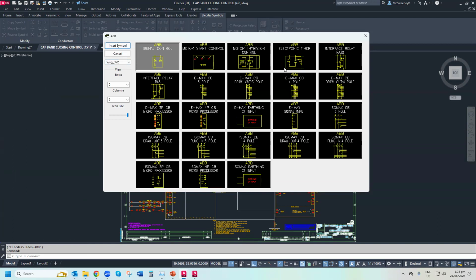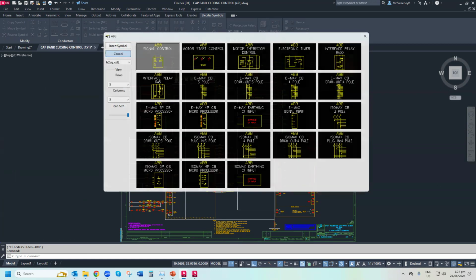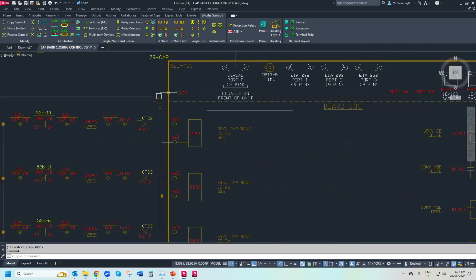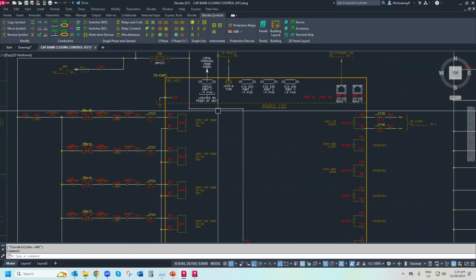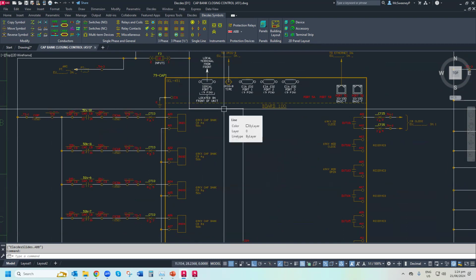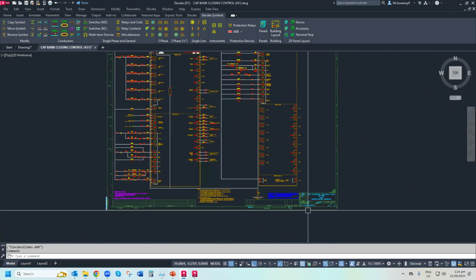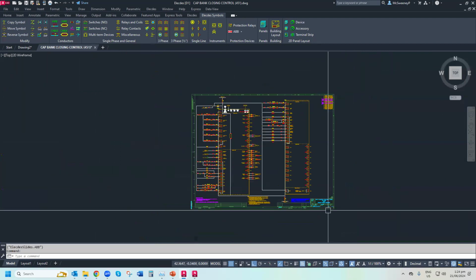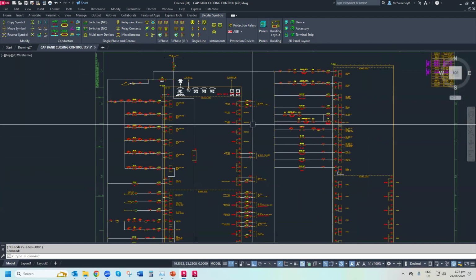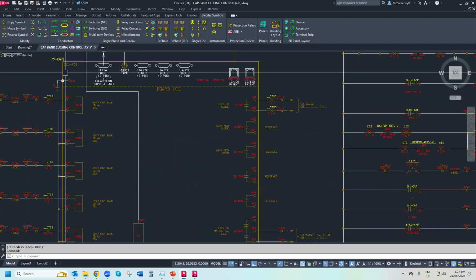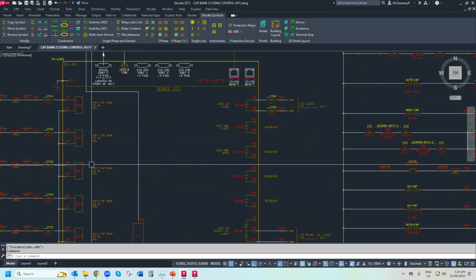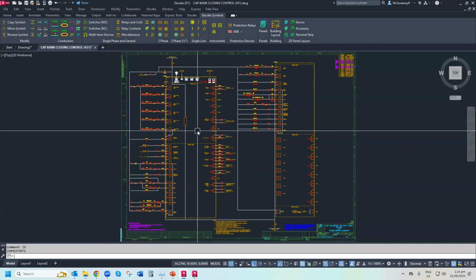It allows you to build any non-standard device, however the heck you want to build it or the customer wants you to build it. So you can have variable numbers of terminals, various bits of graphical and textual information. We're not forcing you to do things our way. And this is a prime example. Schweitzer Engineering in America had our software. We've got all their complicated Schweitzer protection and control relays, which can have 40 subcomponents, some of them. We had all of those, and then they were doing work for somebody up in East Palmerston, and the customer didn't want to have the Schweitzer relays like this. They wanted to do it like this SEL 451, a prime example of a multi-terminal device. It looks like a PLC, but it's not.